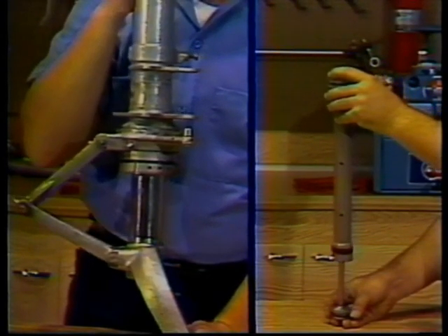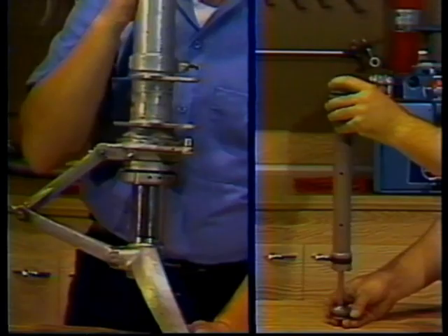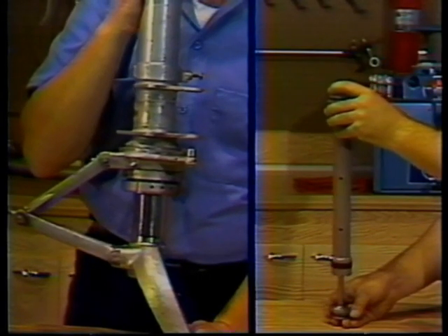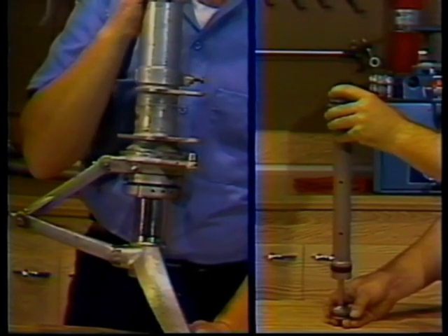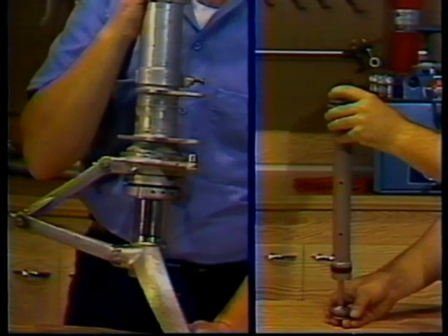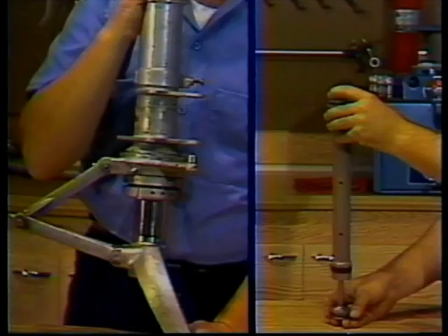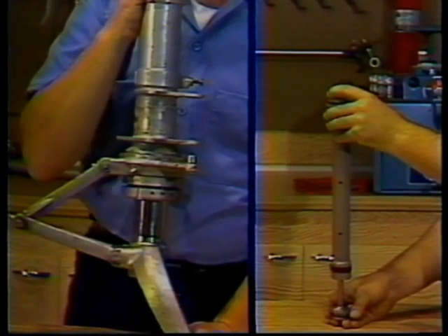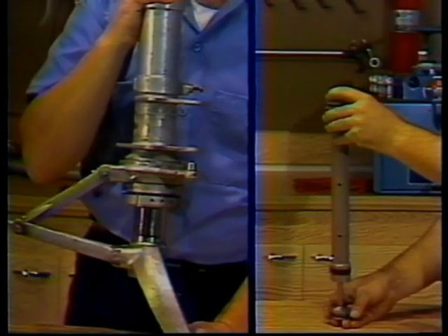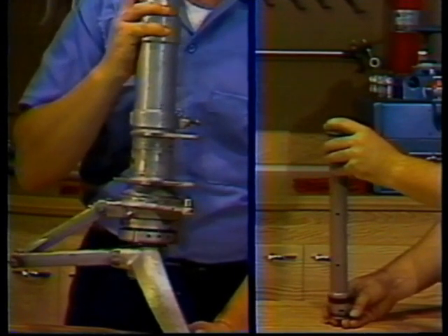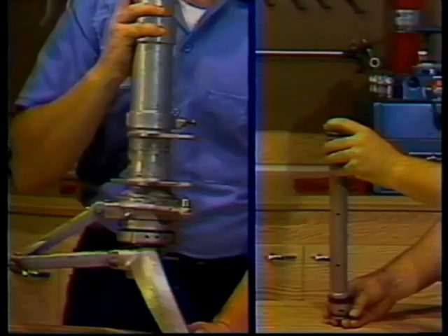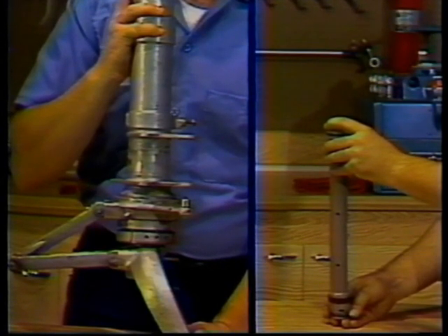As the strut nears the end of the stroke, the air is further compressed. It is the air that carries the weight of the aircraft on the ground. An insufficient amount of either fluid or air in the strut would permit the strut to compress completely or bottom. This could cause damage to the landing gear or the aircraft structure.